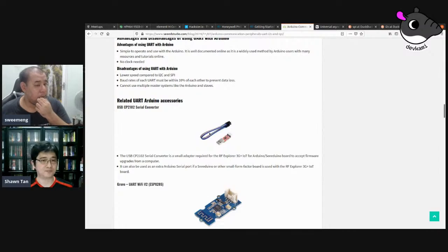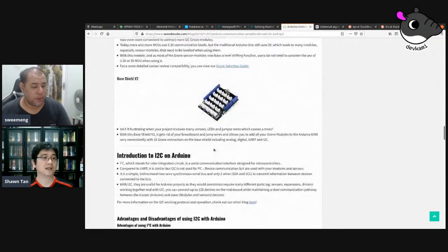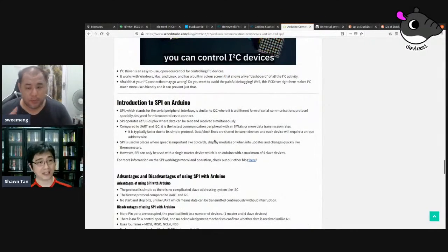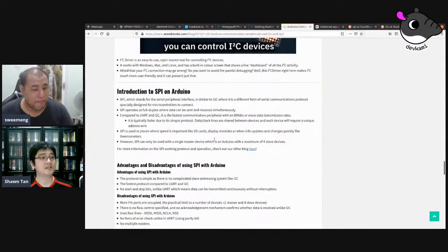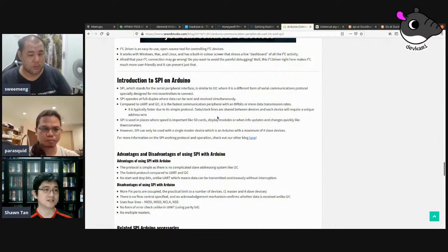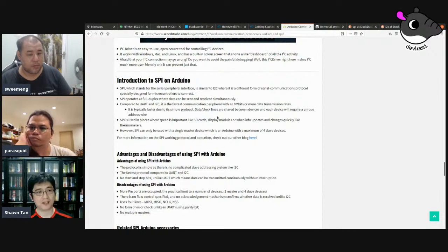It's just transferring the raw data. So that's SPI. SPI is also full duplex. It's full duplex all the time. So you transmit and receive at the same time. So in that sense, it also helps because you sort of double the bandwidth available. Transmit and receive at the same time.